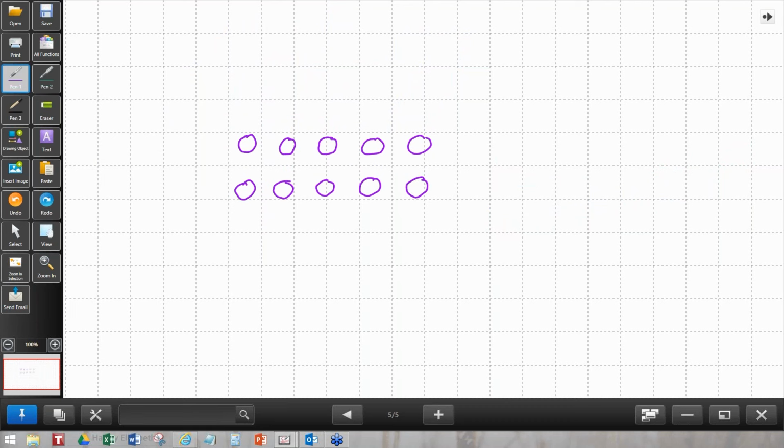There's two general philosophies that are used regularly. One is to put the vias offset from the pads and then connect them with traces. This is the most common way that's used.